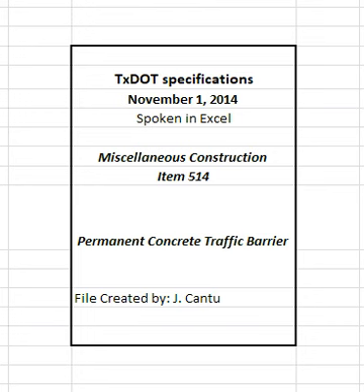Cast barrier in place, slip form barrier, or construct barrier using precast concrete sections unless otherwise shown on the plans. Use forms meeting the requirements of Item 424, precast concrete structural members, fabrication, for precast sections. Wood forms are allowable for curves and transitions. Construct formwork in accordance with Item 420, concrete substructures.